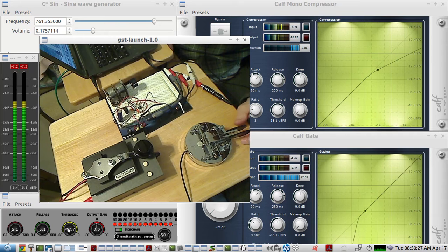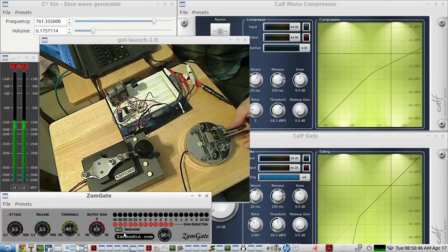Now the threshold setting helps to, when there's enough volume of that side tone coming into the mic jack, trigger the top channel to go through, and the attack and release adjust that rise and fall time for you. Make sure you have the side chain engaged here, so it's showing green. There you go. So that's the mic jack as far as the Morse code goes. And you could use a bug or whatever, just as long as it can key this 555, you're in good shape.